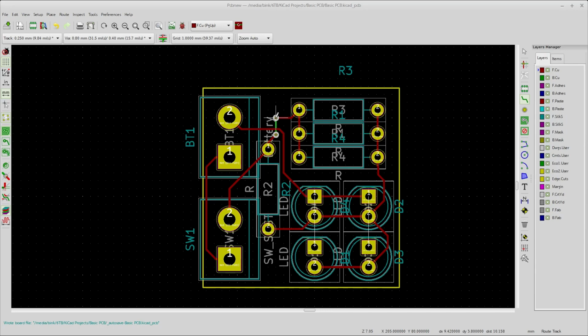I did a via, and it made a via, and then I thought I should click again. It would bring me to the top, and what it did is it seemed to clip off the trace, and then I stopped drawing. So then I had to click on the via, but I was still on the back layer, so then I had to hit page up on the keyboard to bring myself to the front and then connect it. So I'm not really digging that so much, but I'll get used to it.